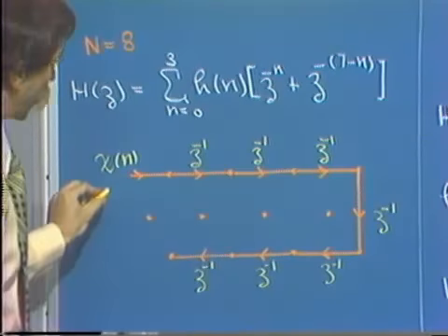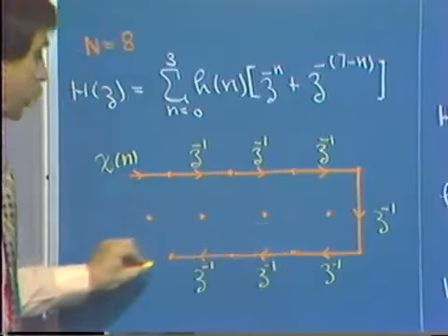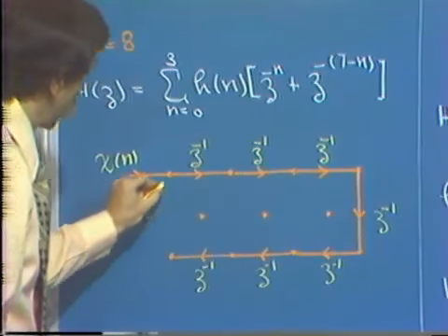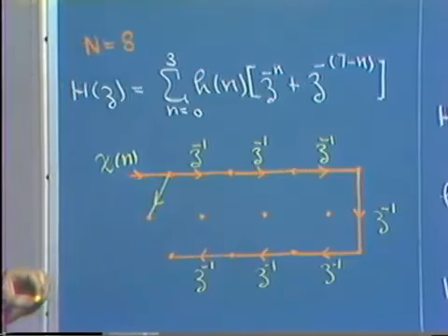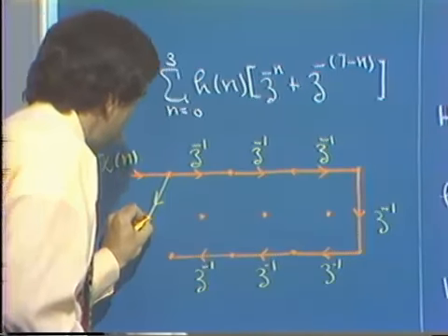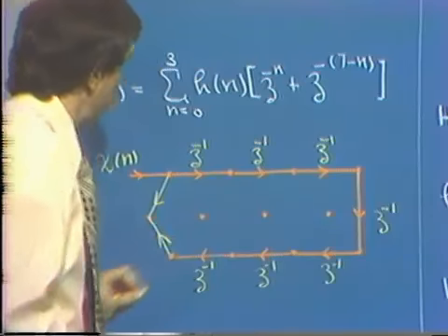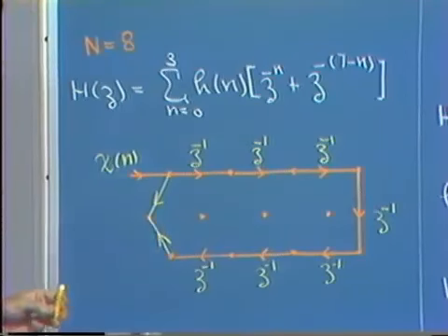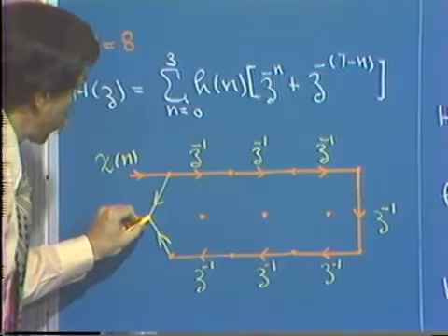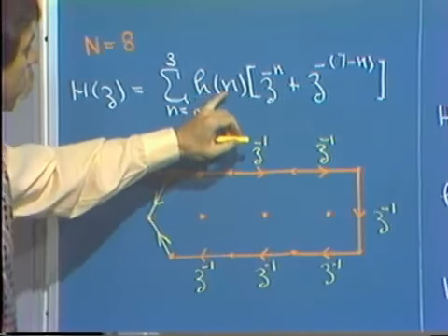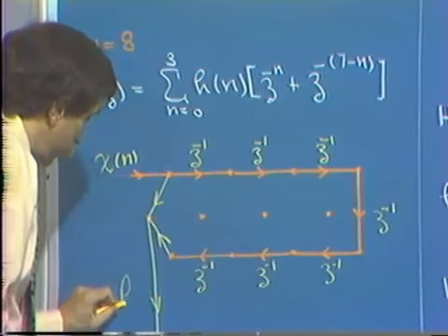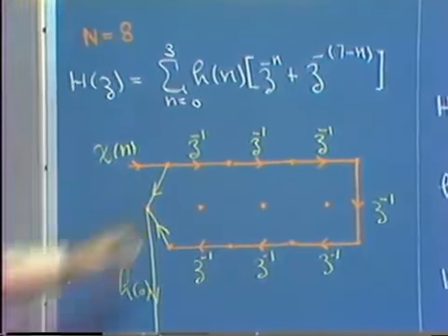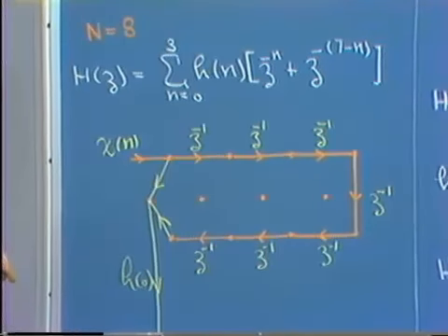So if we consider a chain of delays, as I've drawn here, we have the output before we go through any delays added to the output from the 7th delay. That's looking at this expression for n equals 0, and the result of that summation is multiplied by h of 0 to form the first term in this sum.